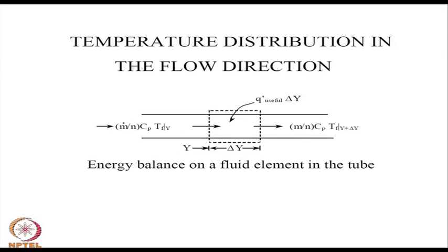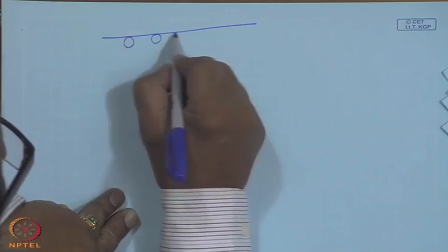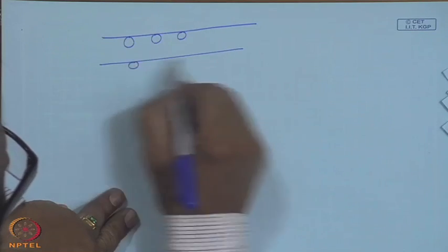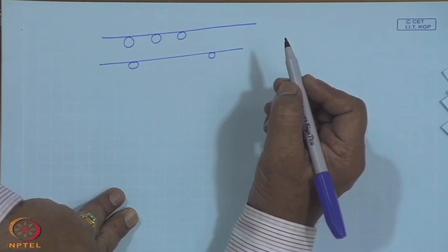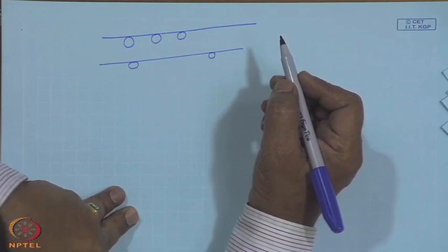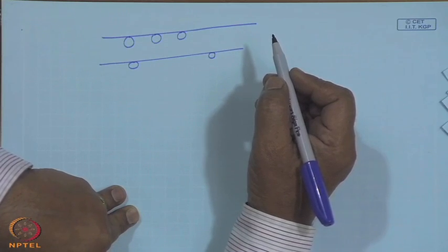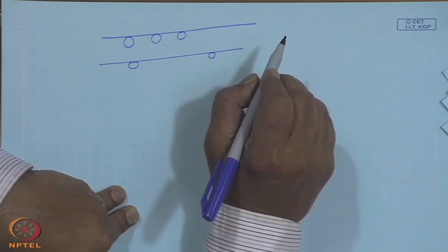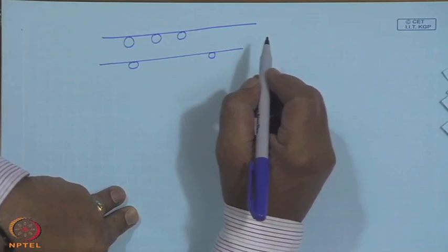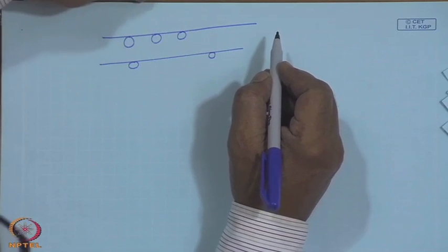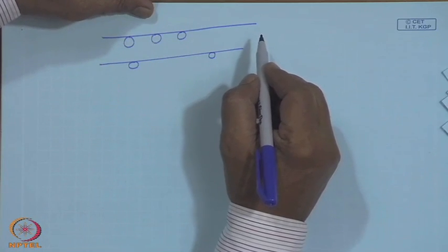So, now we got out of the two one dimensional equations, temperature distribution along the x direction has been obtained. From that, the fin efficiency comes into the picture, which will tell you whether these tubes are pretty close to each other or far off. So, that my fin efficiency will be lower because W minus D will be larger. And of course, the material comes into the picture, the thermal conductivity, and finally, the energy transfer to the fluid will take into account the heat transfer coefficient hfi. So, at a particular fixed y, we know how the temperature varies on the plate in the solar collector.